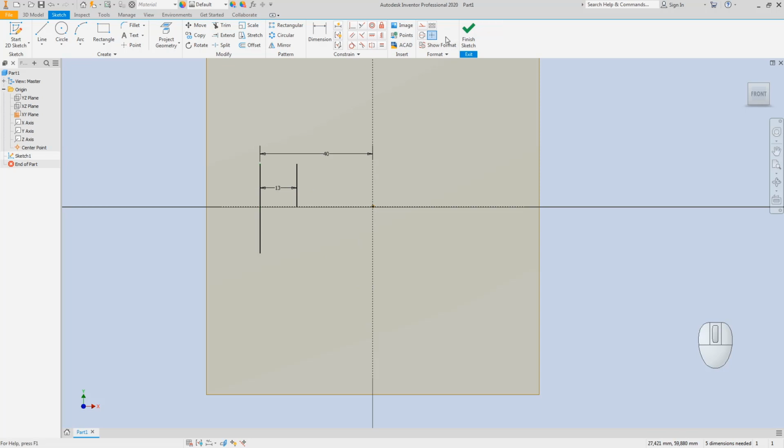which I'm just going to create at this point. To get that point, I will trim this and get this point, and I will create a plane on that point by using a plane passing at this point. Here we have the origin points, the origin planes. As you see, if we use the YZ plane parallel to this point, I can create a new plane to sketch our circles on the ends.